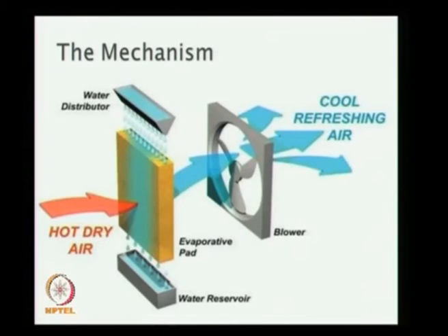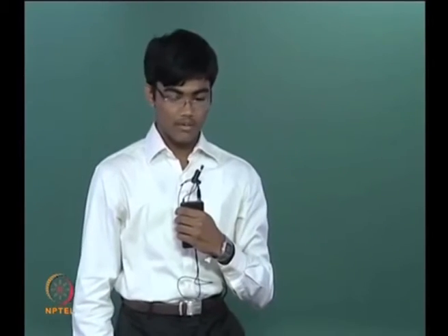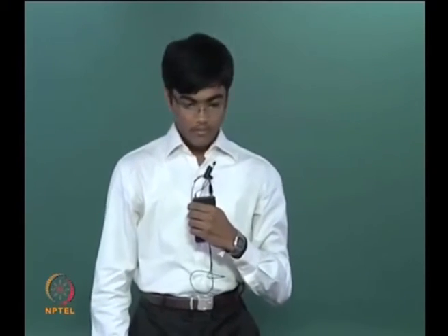These are the main parts of an air cooler. The air cooler works by drawing in outside air through moist filter pads. The air cools down when the water in the filter pads evaporates. The filter pads also filter the impurities such as dust and pollen from the air drawn into them.